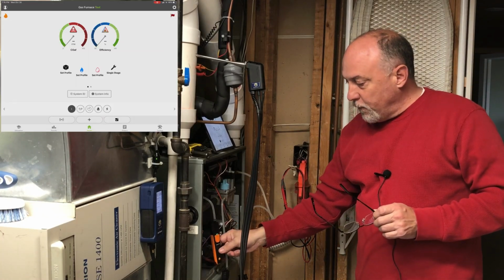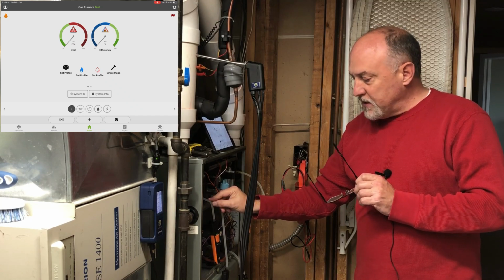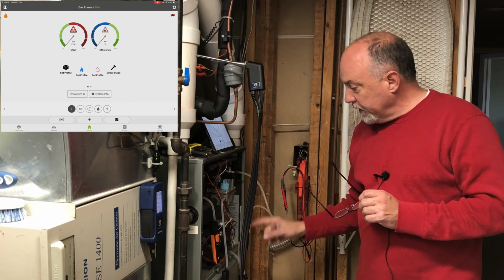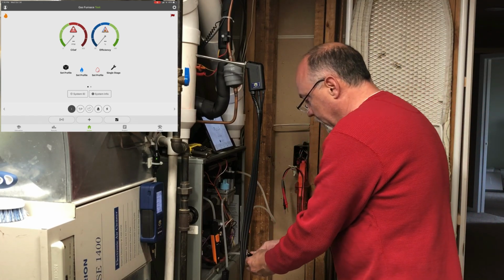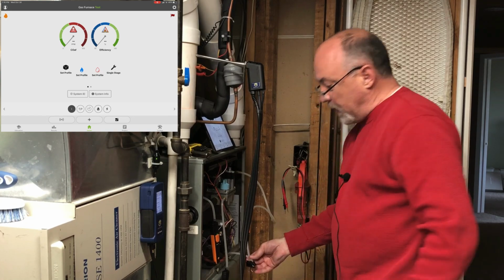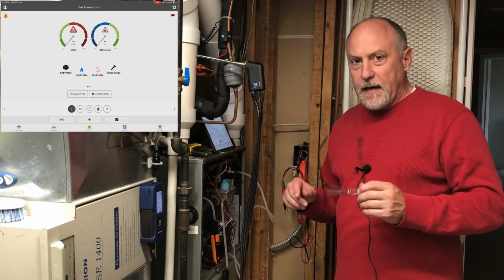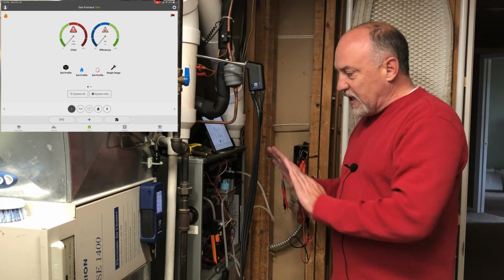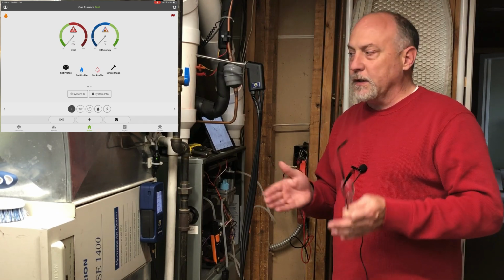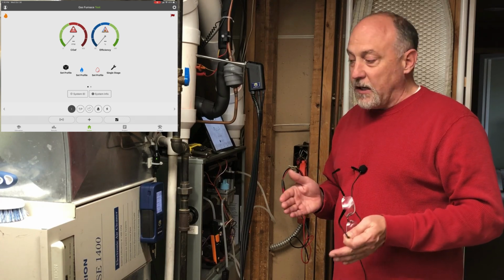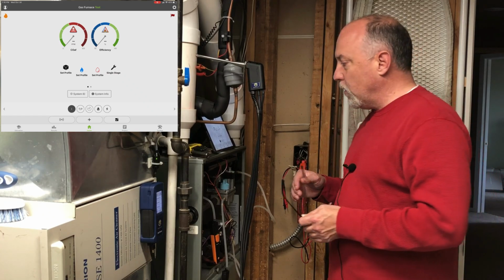I've got over here 4 manometers, so I've got one that's reading the supply static, one is reading my incoming gas pressure. I've got a clip here set up, so I can just clip this off to measure my induced draft pressure when I get ready to do that. And then I've got my manifold pressure here. So I got 4 different manometers, and I like getting everything set up like this so I can do a test pretty quickly. It's mild here right now. I don't want to run the furnace for 4 hours doing a quick test on there. Also, I got my combustion analyzer zeroed out, and we're pretty much ready to roll at this point.